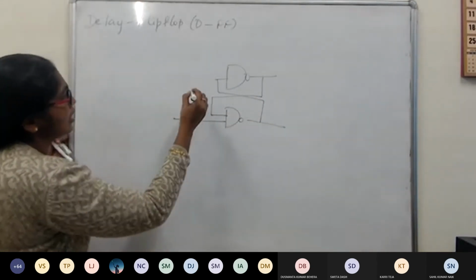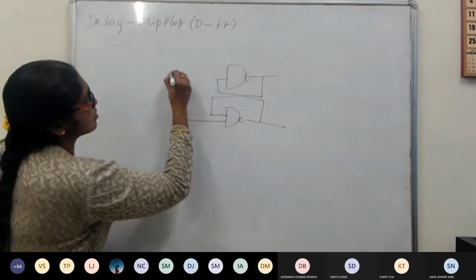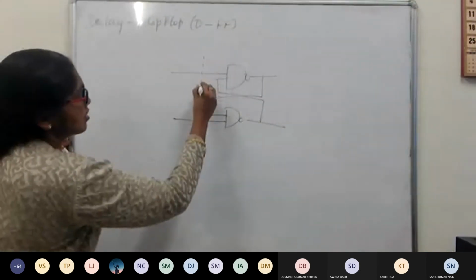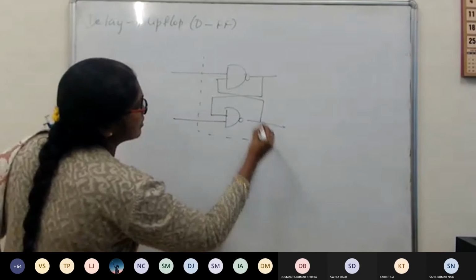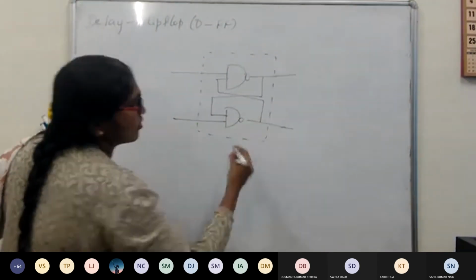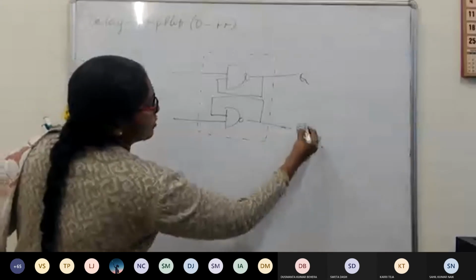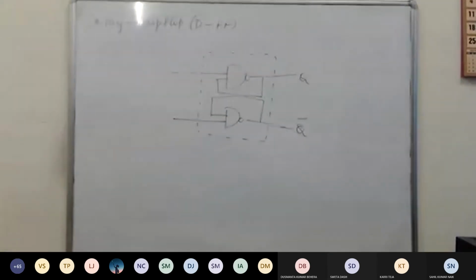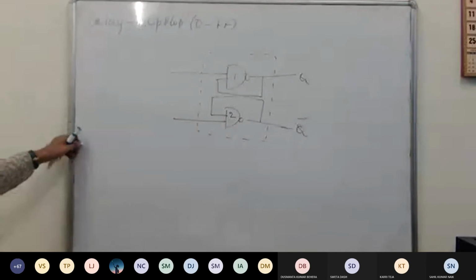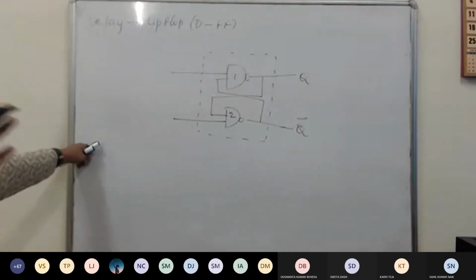Okay, so now this is the latch. This is your original latch. For this one, I am using a NAND operation, Q and Q bar. So instead of NOR, we have NANDs. Okay, so these are the two gates. Now, gate 1, gate 2. Gate 1 and gate 2 will receive the signals externally, S and R, through a clock. Is that correct?